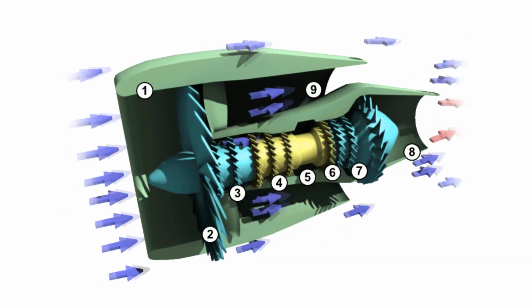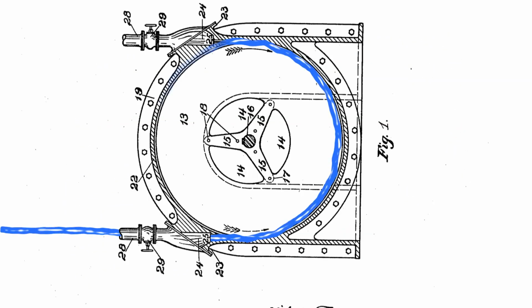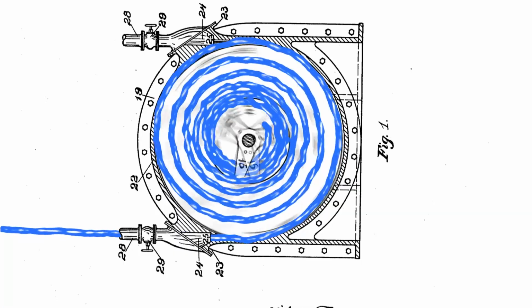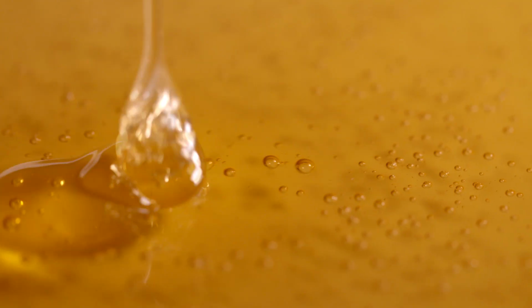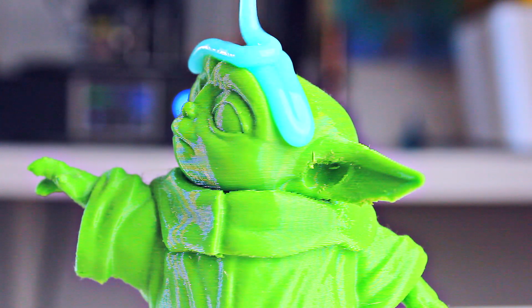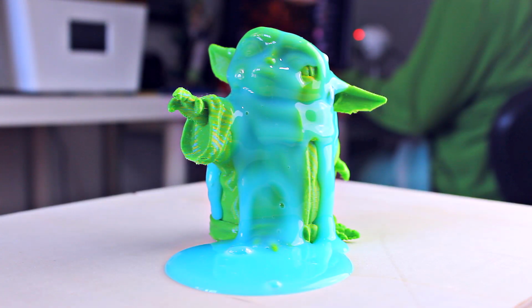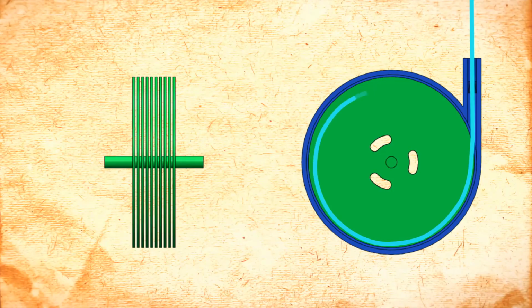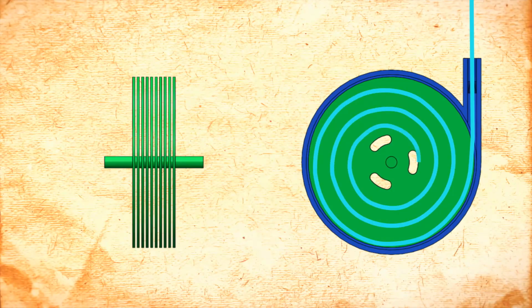Instead of using the fluid to push on the blades, the Tesla turbine uses its viscosity to drag a rotor comprised of several thin discs. Discs? Yeah, discs! Simple circles with a very small thickness. This is possible due to the boundary layer effect, which is a very fancy way of saying that fluids are sticky. They stick themselves to solid objects, and the thicker they are, the stickier they get. This concept is used in the Tesla turbine by forcing the fluid to flow in a spiral that drags the discs in a circular motion.